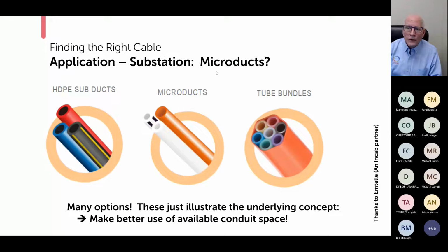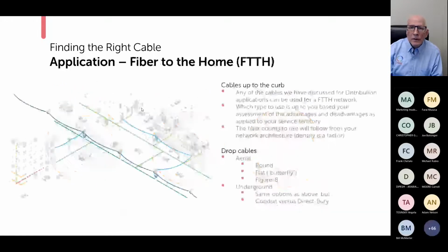Since I mentioned microducts, what are they? Well, as the name implies, they're really small ducts. There are different versions of it: subducts versus true microducts versus tube bundles. There are a lot of options here. That could be its own webinar. For now, I just want to introduce you to the concept. The driving idea is to make better use of available conduit space.